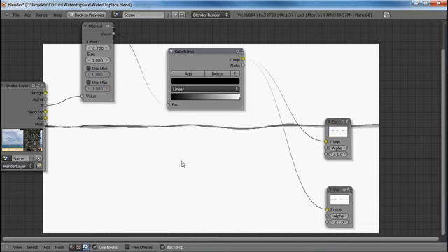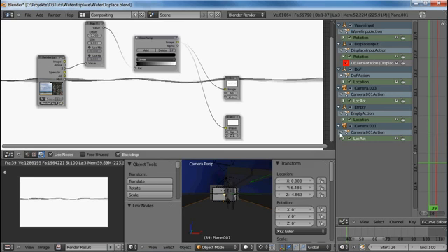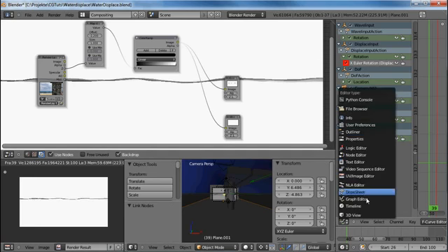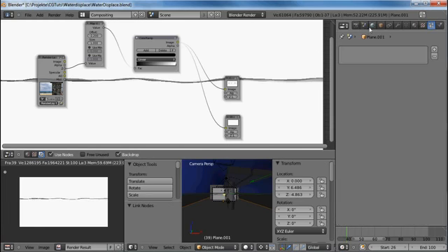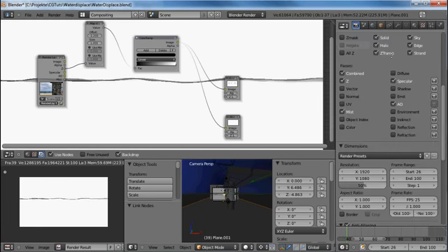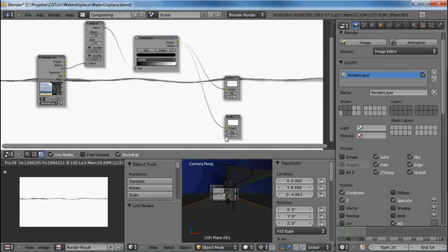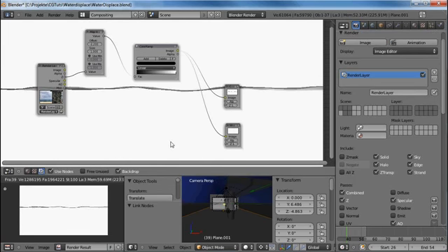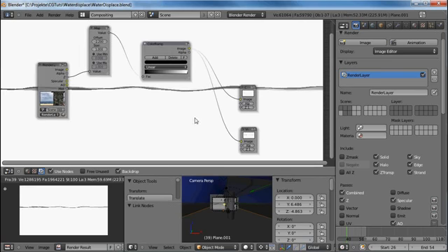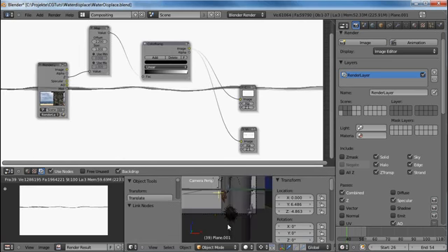Let's just connect the image to the compositor image and render this again. And it will also be from frame 26 to frame 54, same thing as before, the entire passing through the water surface. And of course give them meaningful names, and as I said, I'd recommend to use PNG sequences or TIFF sequences at all time. Okay, this is our blur map for the transition of the water surface.